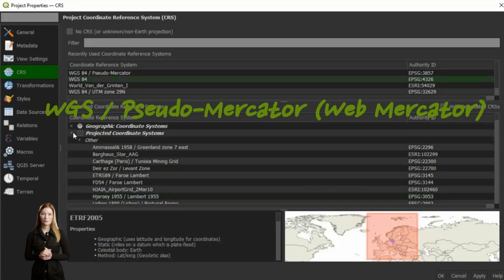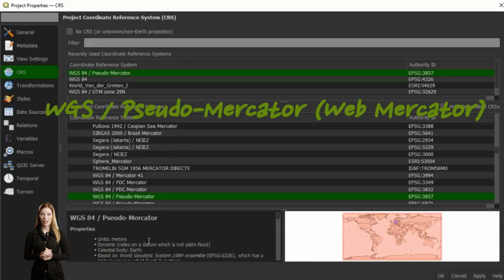Web Mercator is a popular projection used in online mapping such as Bing or Google. The name WGS 84 used together with the Web Mercator systems may cause confusion. In this projected system, the World Geodetic System is used as a datum for the projection. In other words, coordinates are projected onto the Web Mercator grid, transforming the latitude and longitude in degrees into planar XY coordinates expressed in meters on a flat map.